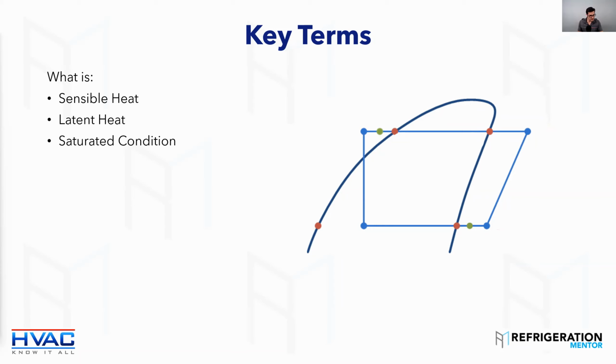So in that evaporator, like Brett said, condenser and evaporator, exactly. And like you said, Gary, you put your gauges on the exit or outlet of the evaporator, on that suction line, and you get that pressure. That would be your, some people say SST. Yep, saturated suction temperature, correct. The one big thing about refrigeration and HVAC is there are a lot of terms. It's kind of like the English language: you say one word and it means five different things. So it's good to understand the different terms. And that's anywhere inside here, where you have both liquid and vapor.